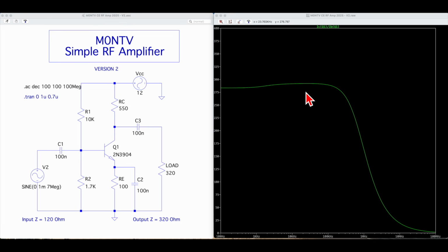I mean, we're getting up to, what are we here? 132 kilohertz. And then once we get to somewhere near 250, 260 kilohertz, it's downhill all the way. So around about 1 megahertz, beta's down to 153 from 290.